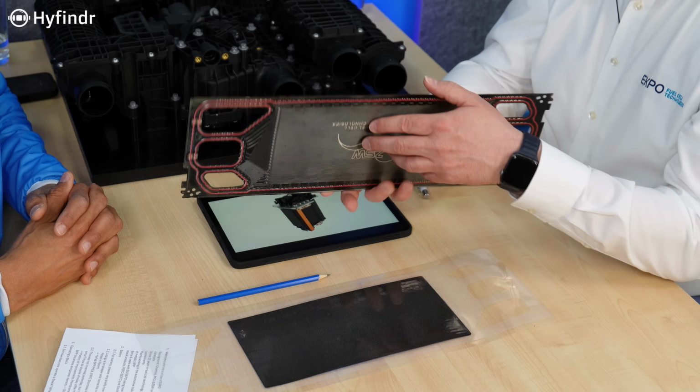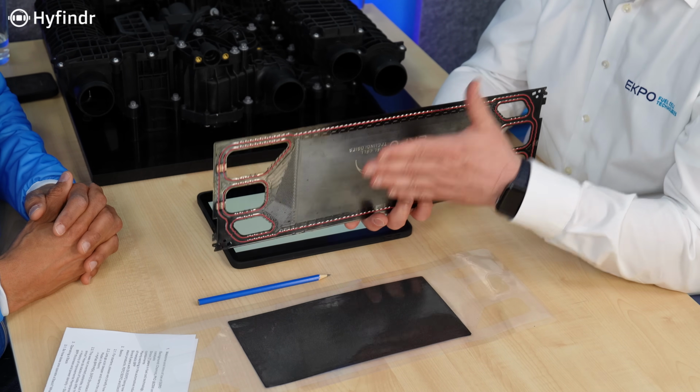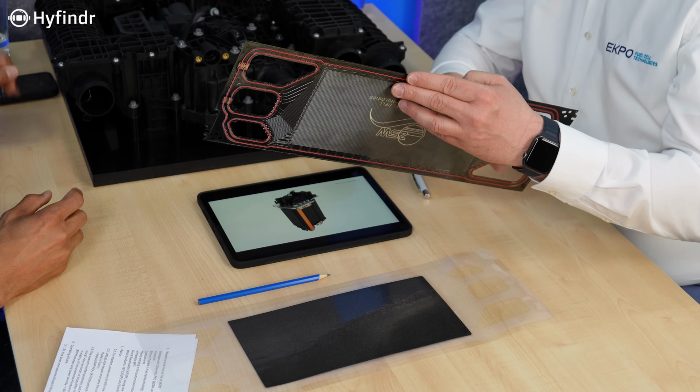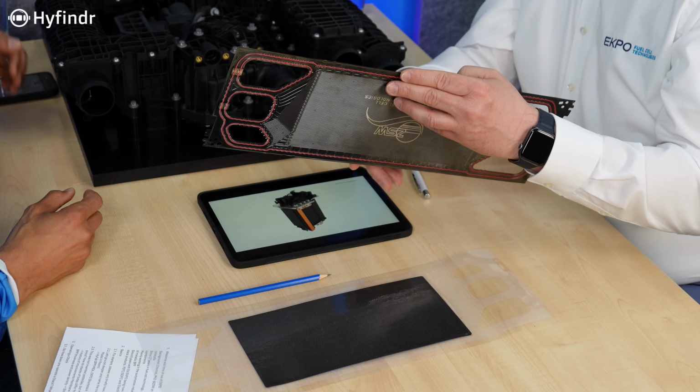In some cases, for example in passenger cars, the stacks are in this direction, what is typically called toast. And in this toast, pancake. Yeah, it's all about breakfast. Nice. So again, this is the issue. If we have the lower part and we want to reject the water here, it's difficult to remove it from the stack in this direction.